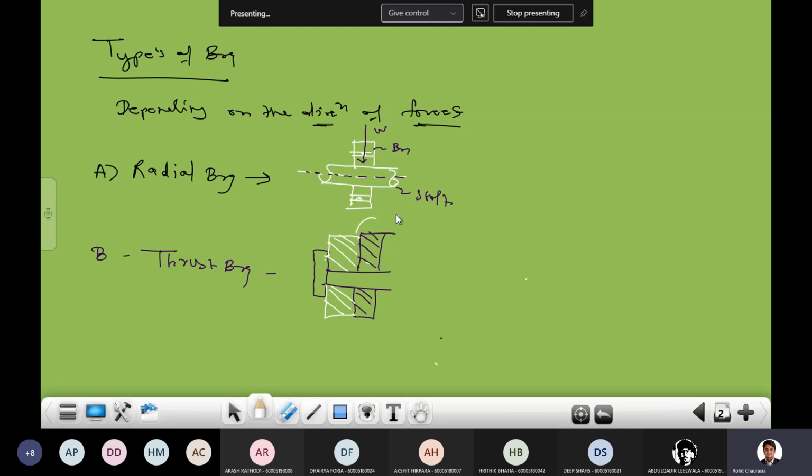तो यहाँ पे जो भी मेरा arrangement रहने वाला है, this arrangement is going to be my bearing. Why are we saying it is a bearing? हम लोग इसको क्यों ऐसा bearing करके consider कर रहे हैं? Because here the load is acting along the axis of the shaft. So when you see a radial one, the load is perpendicular to the axis of the shaft. Here the load is along the axis of the shaft.